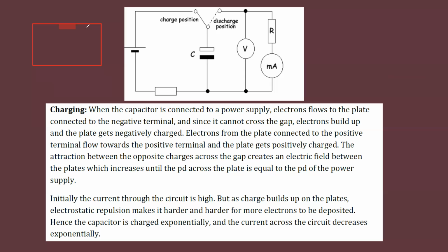It takes a small time to switch off. The reason is that a capacitor is also used there. The moment you close the doors, the capacitor discharges, and as the capacitor is discharging, the light will remain on for some time.